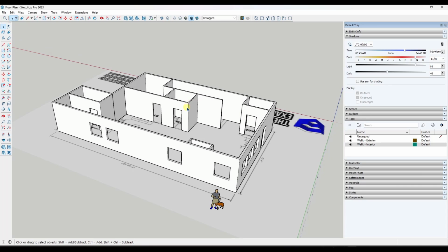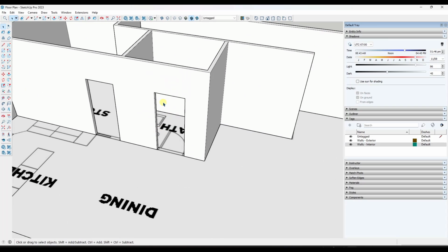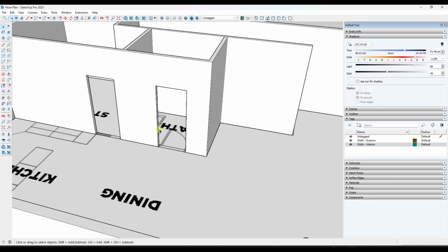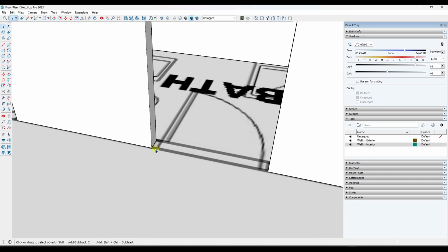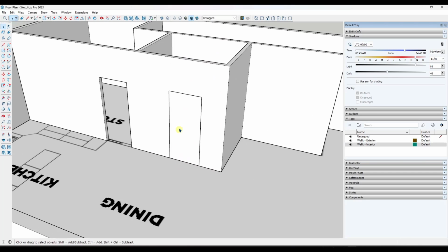To do that, there's a very specific way that you can do this that's going to get you a few benefits. The very first thing that you want to do with something like a door is start by modeling out the frame. You can kind of see the frame from our 2D floor plan right here. Generally speaking, I'm going to tap the R key, mouse over this, and draw a rectangle across this surface.